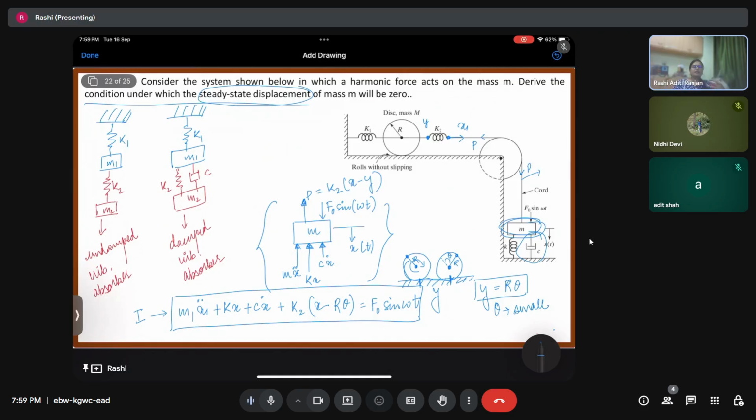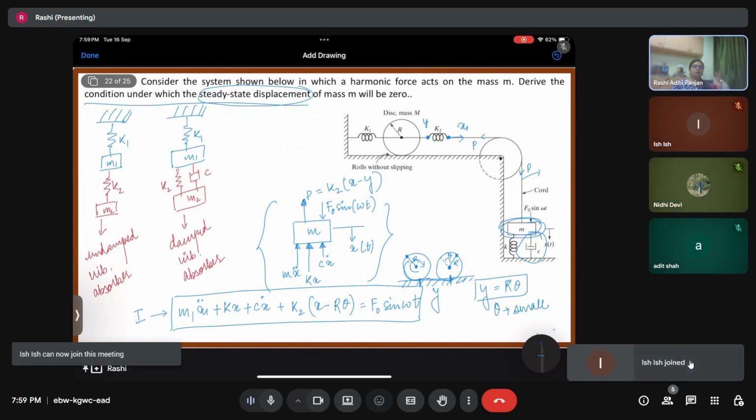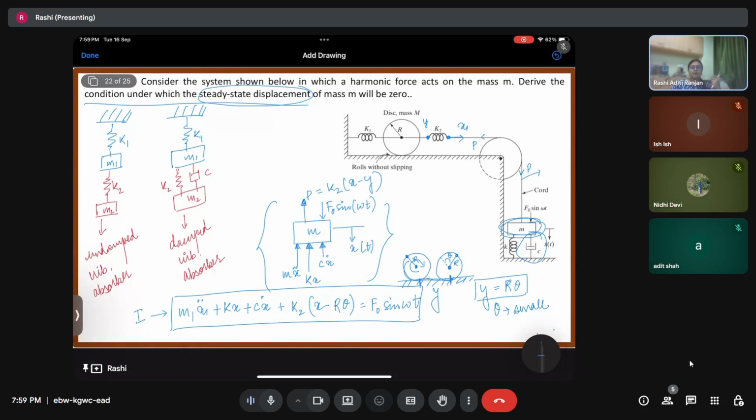Depending upon whether my system is underdamped, overdamped, or critically damped, the time will depend on that. Anyways, it is going to take up the energy which is causing the natural frequency oscillation. So once it takes up that energy, then only the vibration which is present because of the forcing frequency is going to take place, which is what we call the steady state displacement.